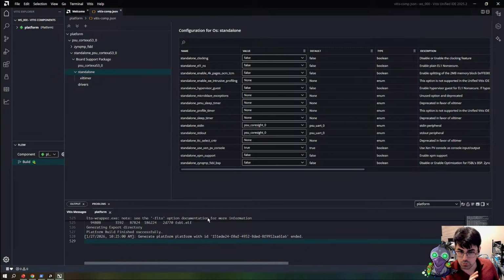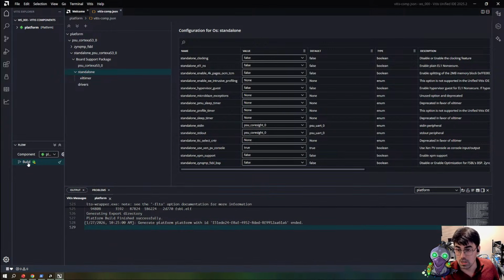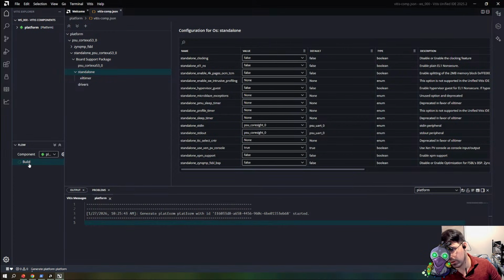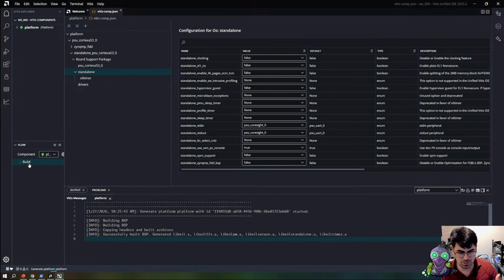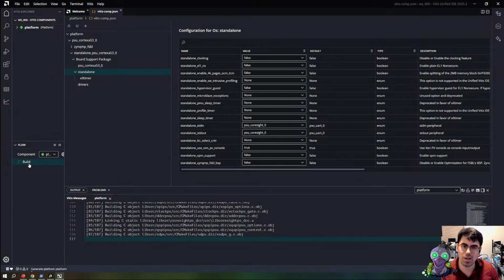So it's great if you just want to do JTAG and the output goes immediately to the Vitis software. We are going to have to rebuild the platform because this defines the standard in and standard out for your processor. If you have multiple UARTs, or want to use CoreSight with 6 different processors, you may want them on different CoreSights or different UARTs, so this can be useful.